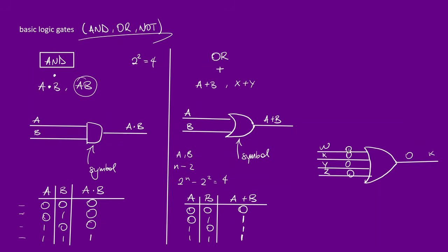Okay, so let's say this is an OR gate, note the symbol with the curved left side. If all of these were low, my output is going to be low. If, however, just one of these became high, then my output is also going to become high. The same thing holds. If Y becomes high, this is going to stay high.